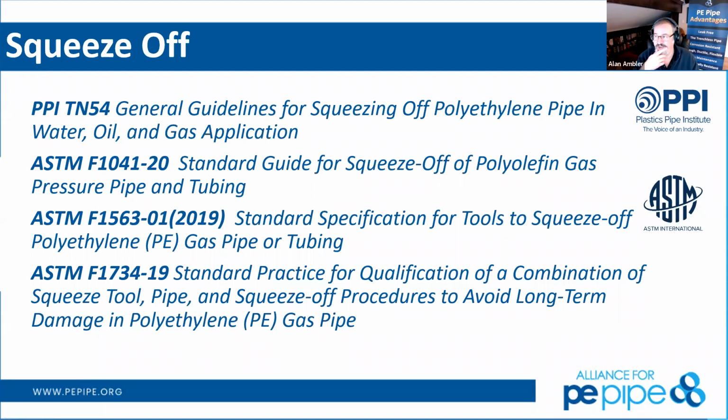So again, if we're rated for 200 PSI, we would be operating that pressure test at that pressure test rating, or 1.5 times the pressure test rating, to look for that. And then the surges, again, are that 1.5 and 2 times. That's for the lifespan of the pipe. There's a difference of what we see in the actual field.